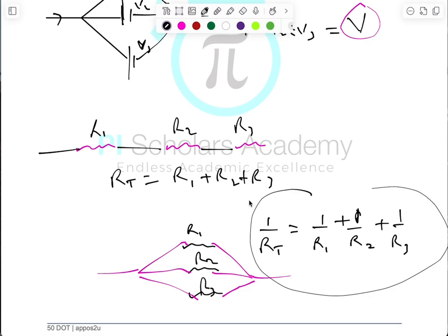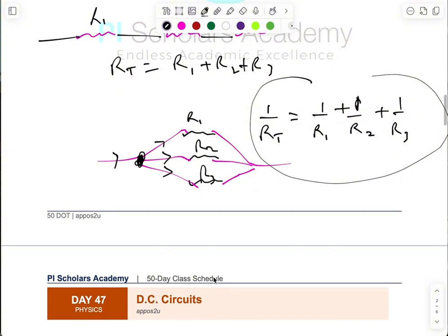However, you can have a situation whereby you have both series connection and parallel connection. You have to properly analyze them together. What determines that something is parallel is not necessarily that they are on top of each other like this. They can be on top of each other and still be in series connection. What determines it is when you trace the movement of current. If you get to a junction where current is splitting, it will have to decide whether it will go like this, or go like this. Therefore, those three paths, anything that is in their way, will be in a parallel connection.